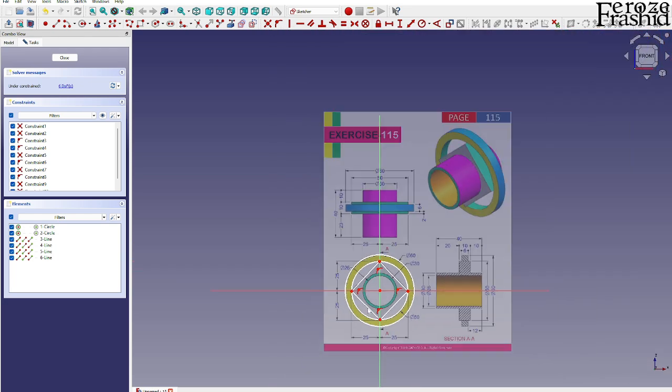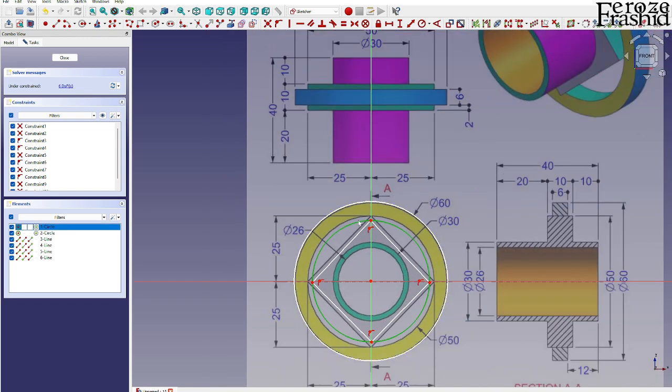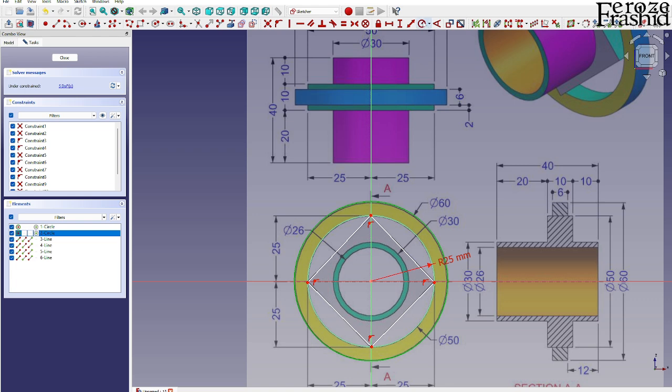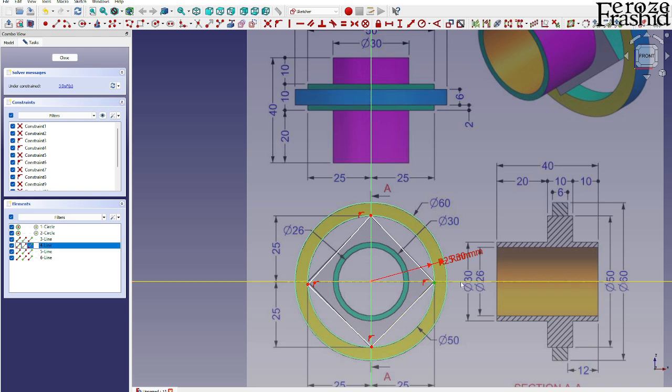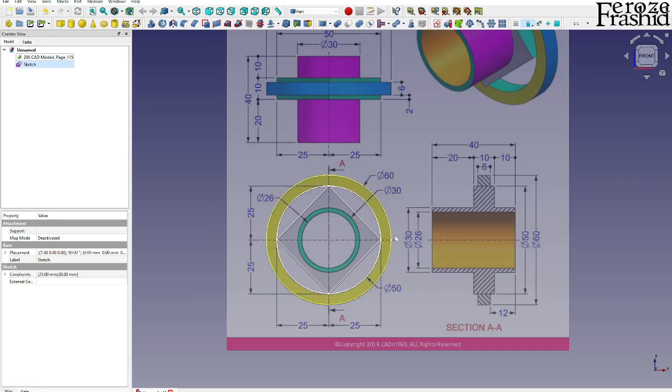Now that we got that part taken care of, let's go ahead and put some constraints on it. This radius, we can make it 25, and the outer one, it would be radius 30. And then we can place these corner points of the rectangle on the axis, all 4 of those, and that will constrain the inside rotated rectangle. So we got that part taken care of.